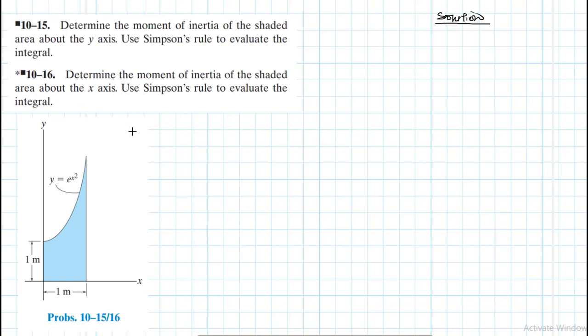Right, and it has so many applications, some of which in structural engineering we use it to calculate the deflections of beams. We use it for buckling load calculations of columns and many other applications. Mathematically, moment of inertia about the x-axis is equal to the integral of y squared dA, and moment of inertia about the y-axis is the integral of x squared dA.